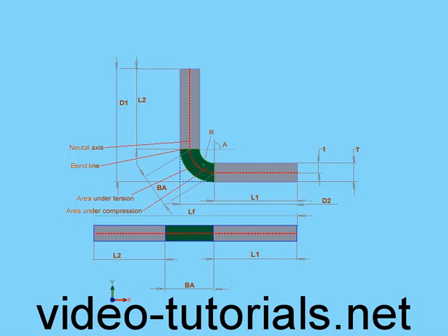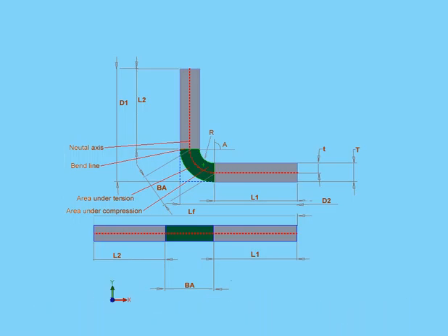If you compare the length of this part in my example here, before and after the bending, you're going to find that they're different. As engineers, if we don't compensate for this variation, the final product won't have accurate dimensions. Of course, this is more critical for parts where you've got to maintain a tighter allowance or precision. If all the variables in my diagram are already making you zone out, fear not. This tutorial is by no means an exhaustive discussion about metal bending theory. However, I do cover some of the basic problems and principles you'll have to deal with regularly when working with sheet metal.